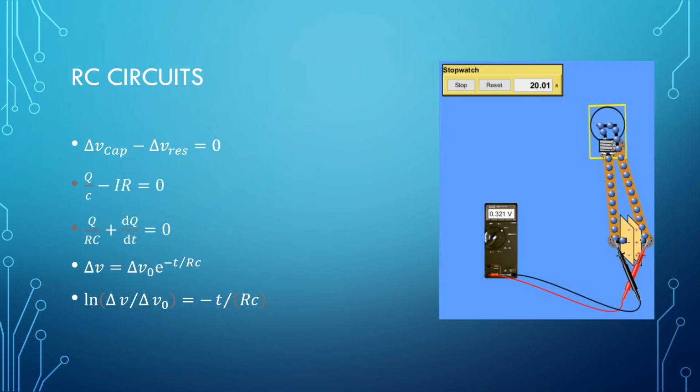Charge a capacitor directly with a battery, which in the simulation charges instantly because there's no resistance. In real life, the wires do have a little bit of resistance, but it's still so small the capacitor charges very fast, which means for that brief moment of time the current's very high, which will generate some heat and can damage some components, but that's not a factor in this simulation.